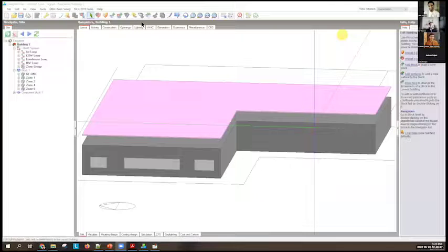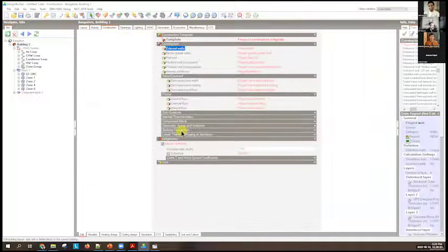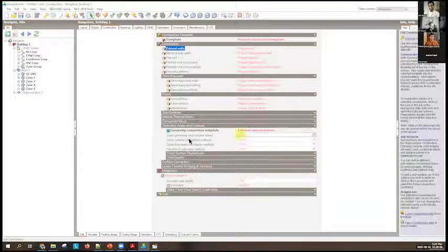Okay. So again, as you learn about it, it gets more complicated in the sense that you have got these, in the construction tab, you have these conventions. So the default convention is that you draw the external wall for the footprint of the building, and then for the partitions you draw the center line.